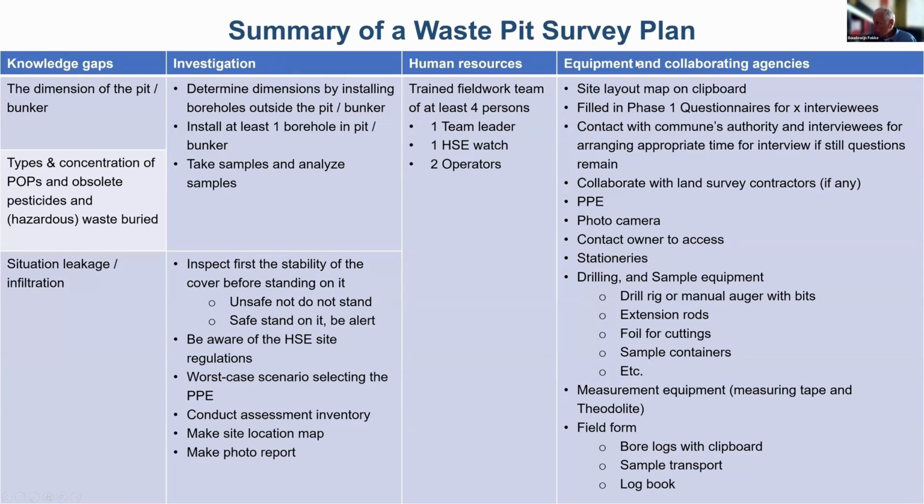And I will only discuss the equipment and collaboration. Here you see drilling equipment, drill rig or manual auger, extension rods, foil for cuttings, sample containers, measurement equipment to make a map, and here field forms, and this is an important aspect, the bore log. Now, if you install a borehole, you always have to describe your soil profile, and you do that on standardized bore logs, and later I will give you an example of such a standardized bore log.